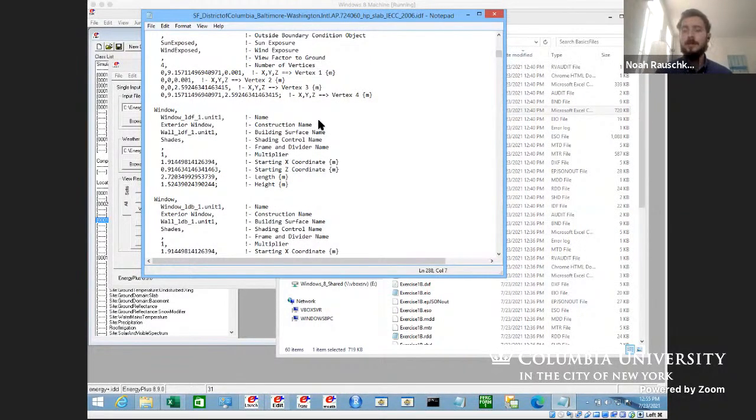You just want to do a load calculation to determine your maximum heating and maximum cooling. So we used a tool made by Trane, which is an air conditioning company, to do load calculations. And if somebody was trying to get LEED for a building and you actually needed a full EnergyPlus simulation, normally somebody else would go and try to build these geometries and run those simulations.